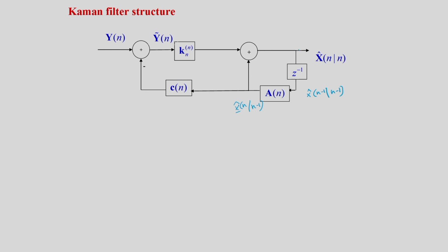Now, to get the estimate, we use this predicted signal. In the observation equation, there is a multiplication of Cn and the state vector. Therefore, this predicted state vector is multiplied by Cn and we will get the predicted input. So, yn we are predicting here. This prediction will result in an error, that is the prediction error. This is the innovation. So, this is the innovation output.